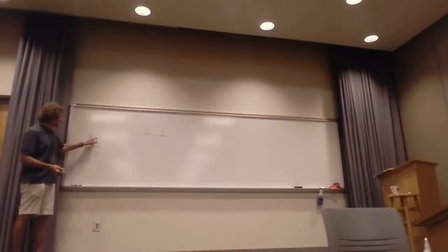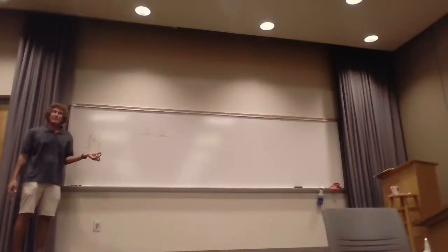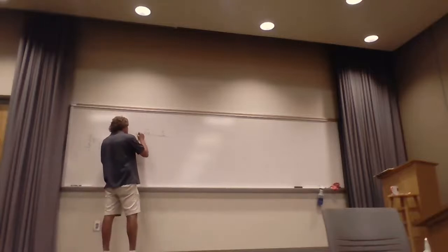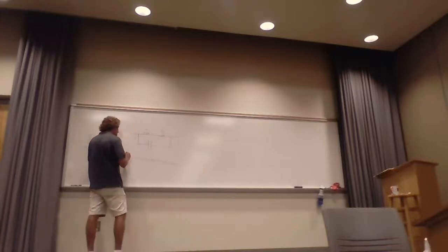There will be a slight voltage difference from here to here. That voltage difference will cause a charge differential, which is given as a capacitance. So you might say there's going to be this weird parallel capacitance across there. But that capacitance lands itself here. Now that's not exactly perfectly correct, but it's a good way to estimate what goes on.